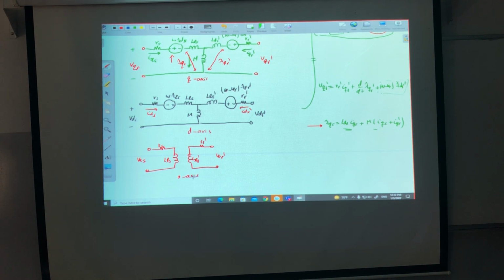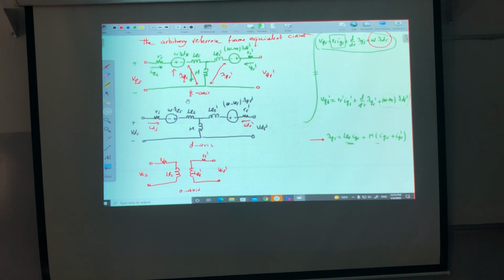So this is the equivalent circuit. By the way, from here we can derive the per-phase equivalent circuit, the steady state, the famous one. Now, until here, let's state some advantages of the reference frame. The first one, we simplify the voltage equations. The second one, the inductances now become constant. The third one? Yeah, if the voltage equation is very simple, simply I can get the equivalent circuit.